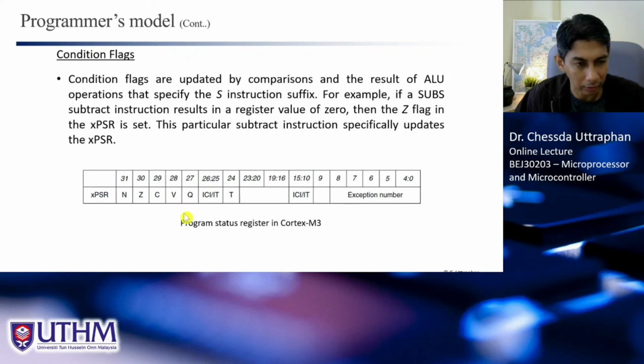The saturation instruction, once we perform it, for example, when we add numbers in 4-bit operation, the maximum number will be positive 7, right? We will never get 8. So when we add, for example, 5 plus 3, the result should be 8, right?